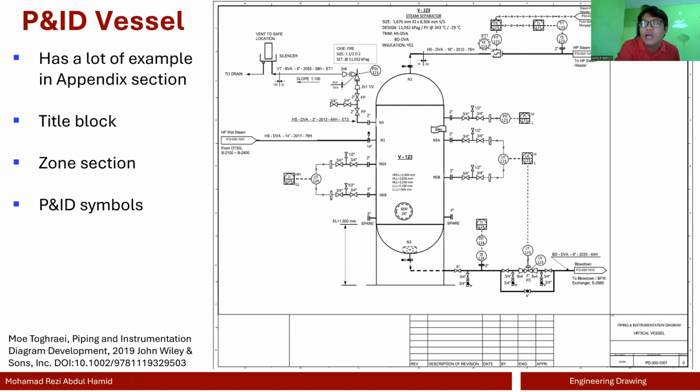It basically allows you to identify a certain component in the drawing, especially when we deal with a very complex and large drawing. It allows the reader to focus specifically on that particular area. For example, let's say you make a correction or revision on this drawing. In the note section you write down, for example, that a gate valve has been added to nozzle number 4.